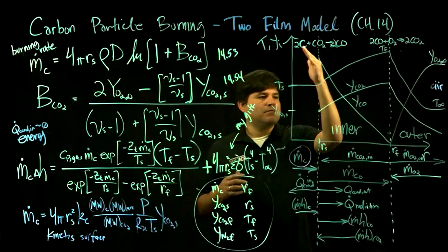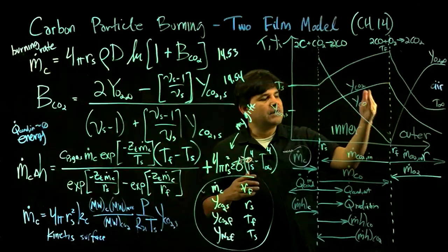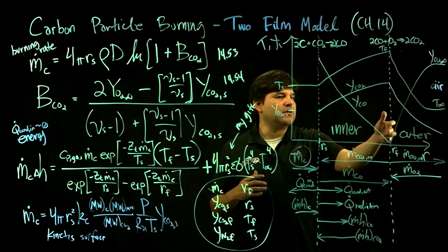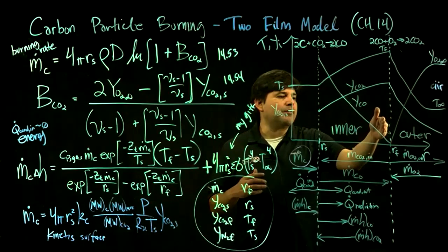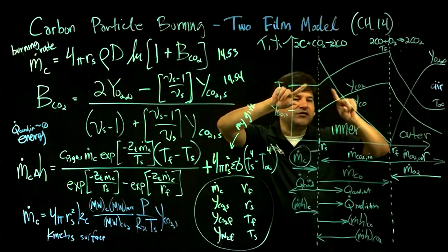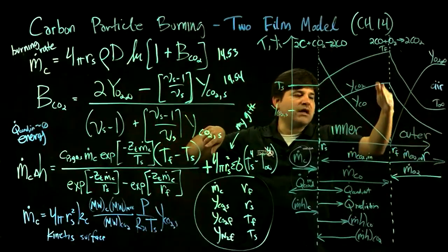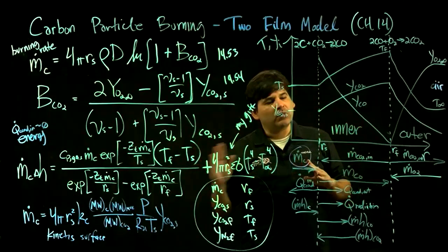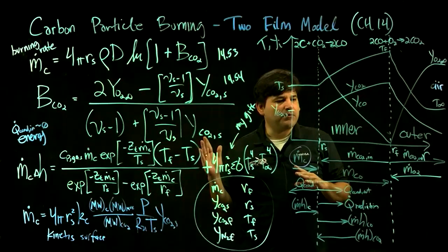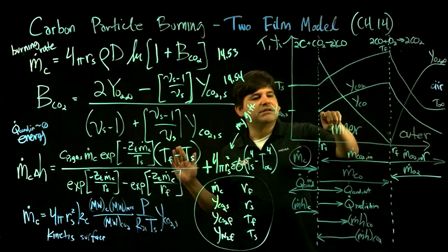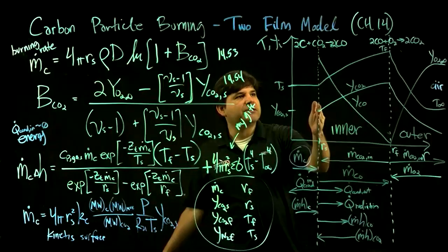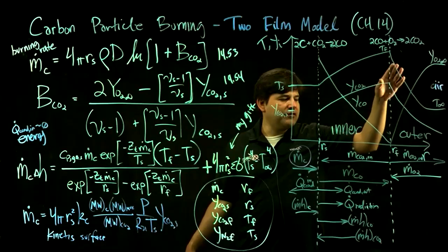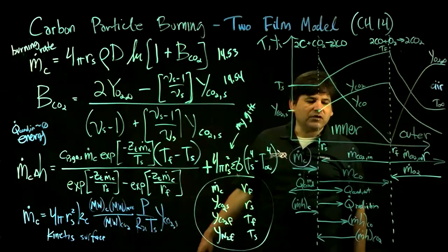We captured that for a solid fuel feeding a flame, one important fuel is CO. And in this model, the CO burns to produce CO2. That CO2 diffuses outwards from the flame, going in two directions. In one direction, it's towards the surface of the carbon. The other direction is to the surroundings. When that CO2 approaches the carbon surface, it produces more CO. Then that CO can go on to burn at the flame away from the surface. And then the oxygen comes from the far stream.